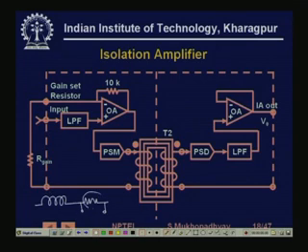Although this potential difference is proportional to the current, these points can be at very high potentials compared to ground, at hundreds of volts. So it's important that you don't directly connect such signals into your electronic circuits. It will even damage the circuit.